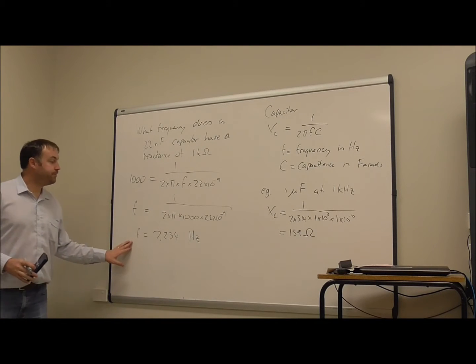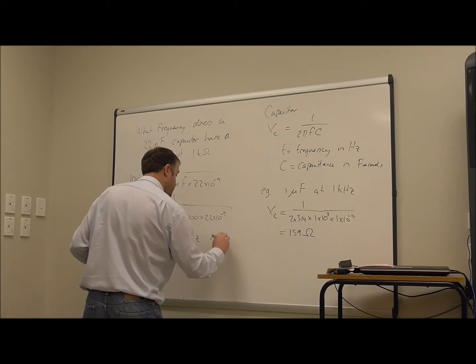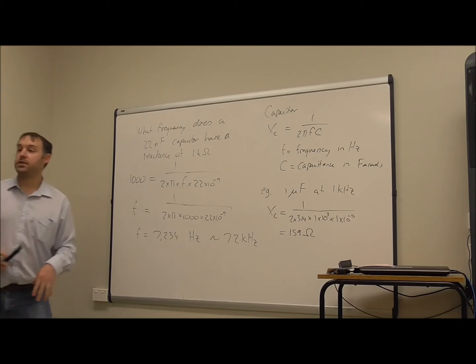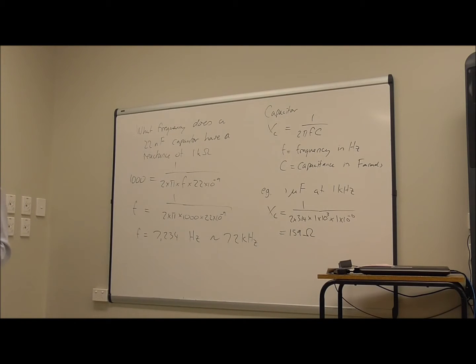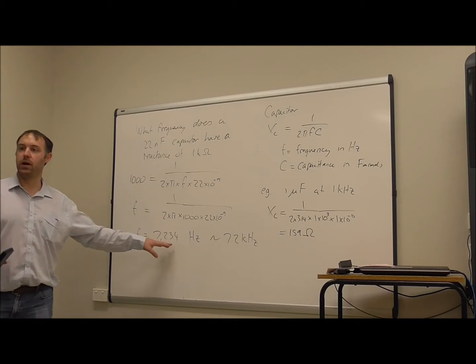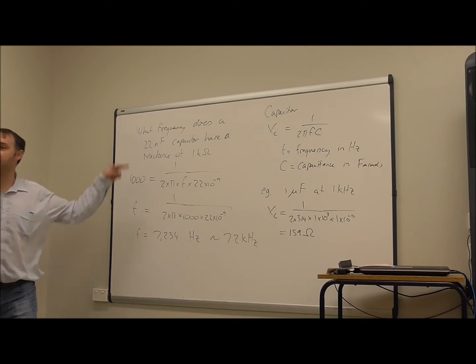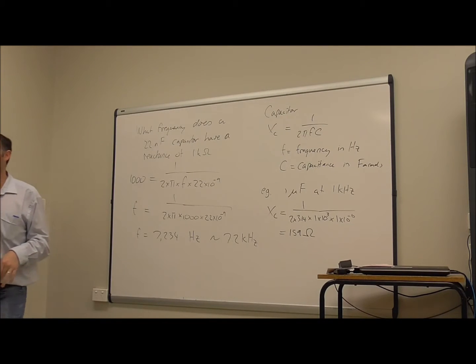Okay, so quite often we can satisfy ourselves with really 2, maybe 3 significant figures. We don't need to go too nuts on the accuracy here, so I'm not even going to 0.1 of a hertz. That's mainly because the accuracy of our capacitors and our resistors isn't really that high.